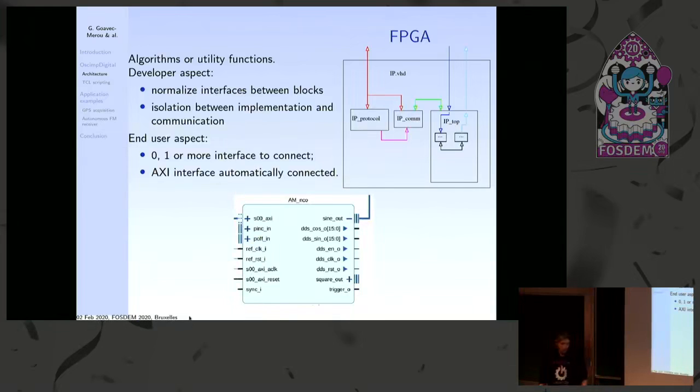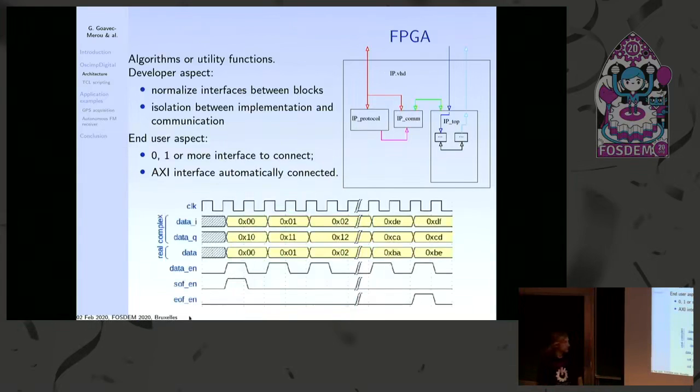These signals are there to be sure to have correct coherence across clock domains. More precisely about content: on a complex signal, you have an I/Q data bus, on a real signal just one data bus, and an enable to specify when a new data is available to be processed. And you have some control signals, start of frame and stop of frame. Finally, an A to D converter or D to A converter has just an infinite data stream. No start, no stop, nothing.